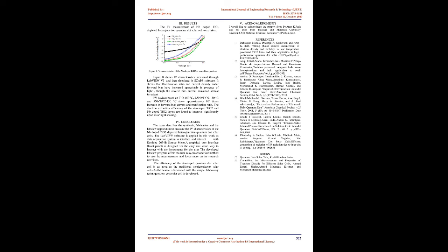The program enters into a for loop and iterates in steps until the difference between final voltage and initial voltage is 0. For each iteration it communicates with the Keithley 2634B source meter. The first VISA Write of LabVIEW fetches the current output from the source meter and stores it into the buffer. The second VISA Write reads the voltage provided by the mathematical logic for the loop. After a waiting period is over, VISA reads the buffers and plots a graph of current against voltage.